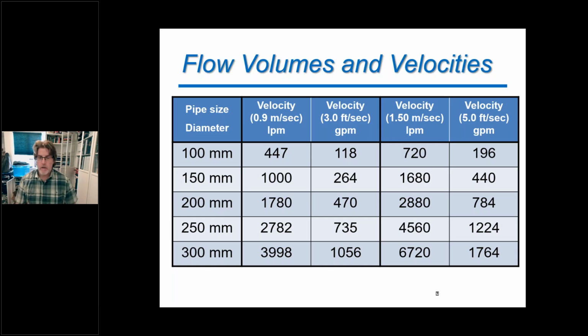I'm happy. I'm achieving really good scouring. Now, if I'm not able to hit these goals, I might have to look at, do I need to open up the other ear on the hydrant? Do I need to flush out of both of the 2.5-inch ports at the same time to give myself a little bit more flow? If I'm going to do that, once again, I need a diffuser on both ends of the hydrant. They do also make diffusers that go off of the pumper port on the hydrant. So if you have that capability to go through there, you can get more flow that way.